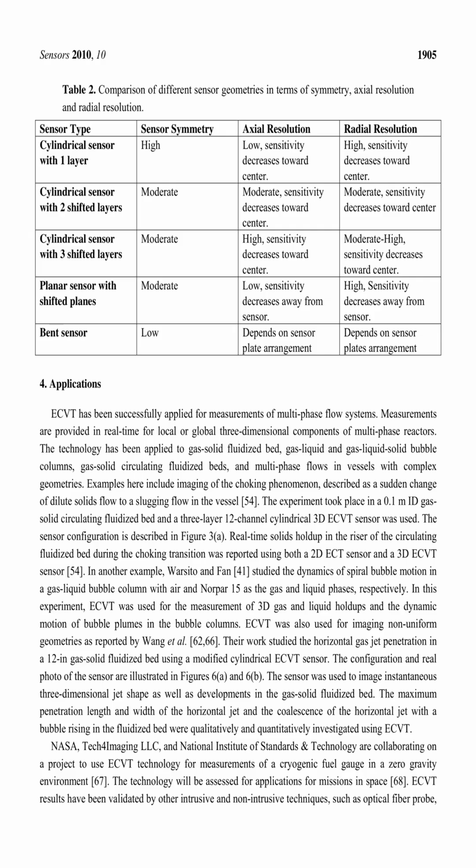The experiment took place in a 0.1 meter ID gas-solid fluidized bed, and a 3-layer 12-channel cylindrical 3D ECVT sensor was used. The sensor configuration is described in Figure 3A. Real-time solids holdup in the riser of the circulating fluidized bed during the choking transition was reported using both a 2D ECT sensor and a 3D ECVT sensor.